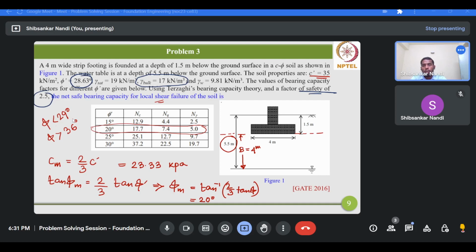Now for cohesive frictional deposit, this prediction will be based on the load settlement behavior. So if the failure is taking place at a very small strain level, that is less than 5%, then you can expect general shear failure is prevailing. However, if there is no failure for a range of strain in the order of 10 to 20%, or you are observing failure beyond that range, it will be governed by local shear failure.